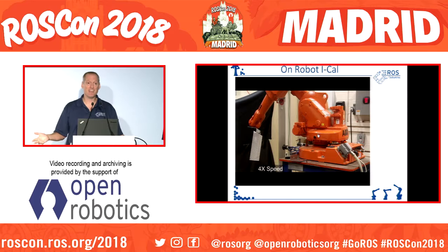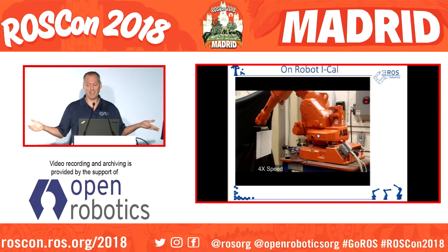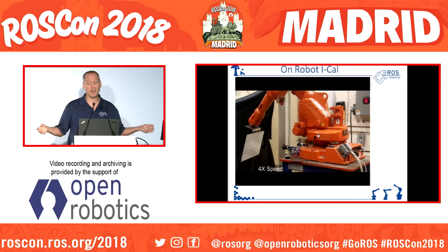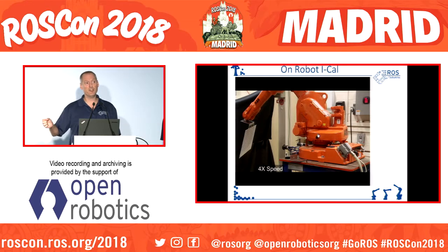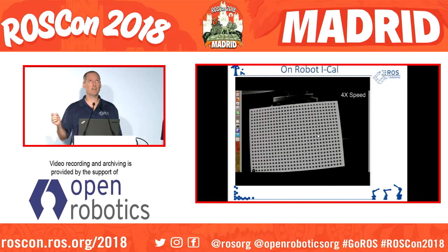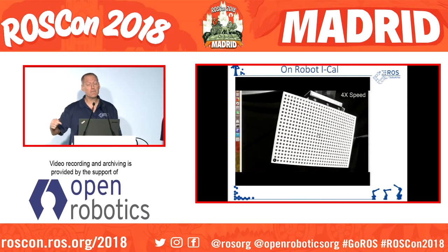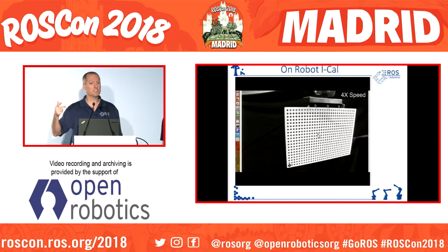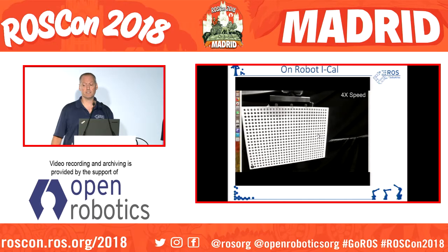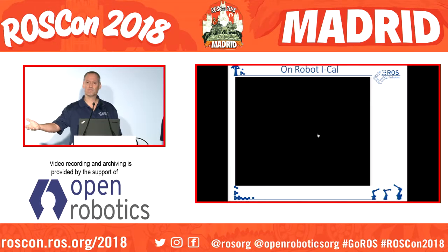And we do the same thing in terms of intrinsic calibration using a target on a robot. So it's a different node, different package, or not package, different node. But it has the same exact type of service calls, just a different base name. It says take a picture, and then you have to move the robot, and it takes the picture again and adds all the observations you want. Compute your covariance whenever you're ready, and then see if you're good and add more pictures if you're not.